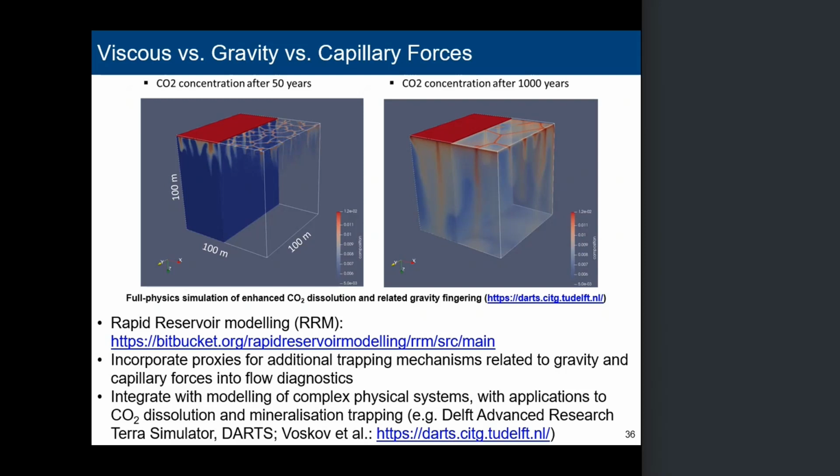We have worked on other projects with more complicated grids, including some that crawl along with the fluid front through time and track changes in pressure and saturations. They're great, but they're not computationally cheap. So here we use a very simple Cartesian grid. We can play around with the resolution to make sure we capture what we want. It's also very stable, fast and numerically simple. We have an aspiration to get the more complex gridding back in, but we ran into practical problems, so it's on the wish list, but it's not there yet.